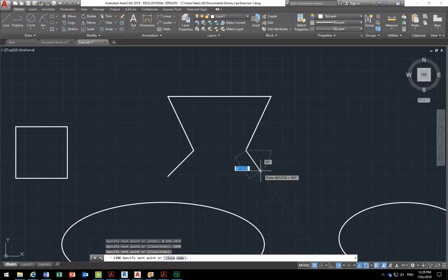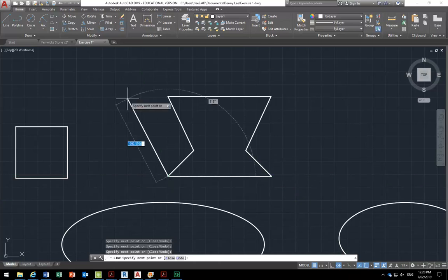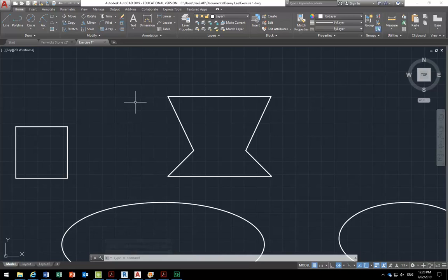Okay, so I can use the same method now to get this final point again, hovering on that end point, over to the right, and then we'll come down, this time 45 degrees. And then back to the left. So, yeah, it's a brilliant thing. I mean, I've done trigonometry, but I haven't had to use those formulas for 20 years because AutoCAD will do it all for you. It draws more accurately than you ever need to take your measurements, and it does all the hard work for you, but you just need to understand how it's getting there.